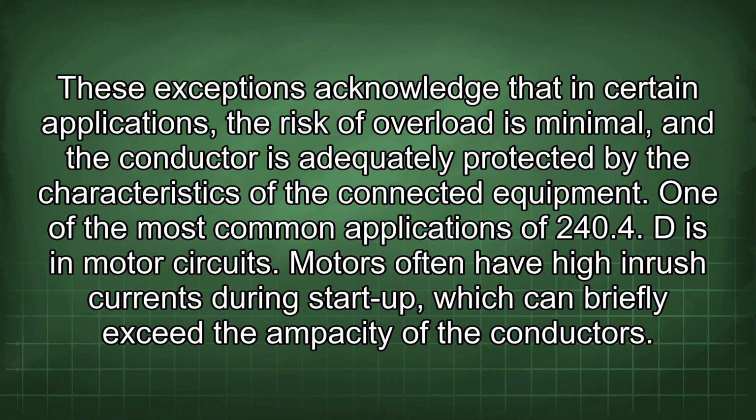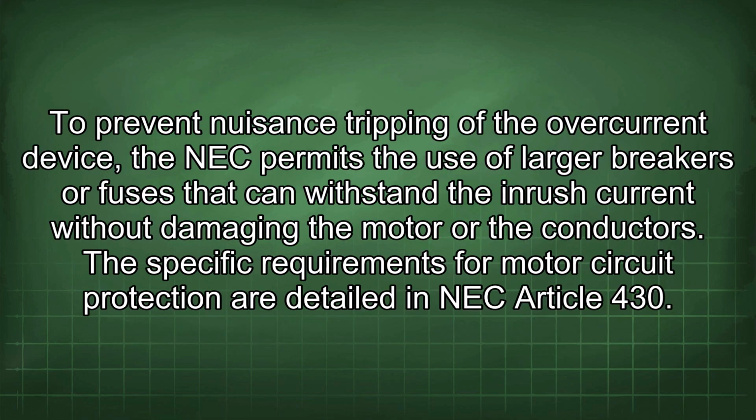One of the most common applications of 240.4(D) is in motor circuits. Motors often have high inrush currents during startup, which can briefly exceed the ampacity of the conductors. To prevent nuisance tripping of the overcurrent device, the NEC permits the use of larger breakers or fuses that can withstand the inrush current without damaging the motor or the conductors.